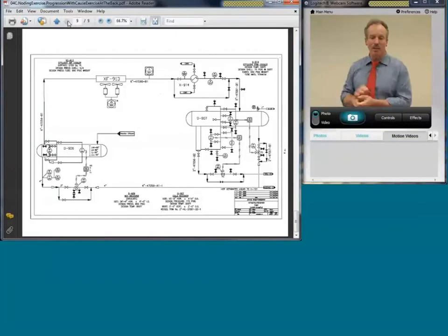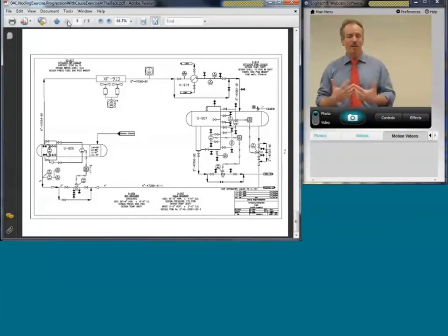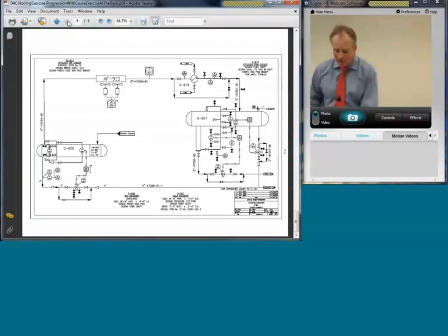Okay, good. It's a small tank where you've got level control, where the vapors are going off to an air cooler, a trim cooler, and then to another process vessel where you've got, in this case, water and hydrocarbons being separated, water coming off to the boot on the left and hydrocarbons coming off to the boot on the right. So what I'd like to do is go through that and first of all talk about what the nodes would be, and then secondly talk about what kind of causes would make sense.